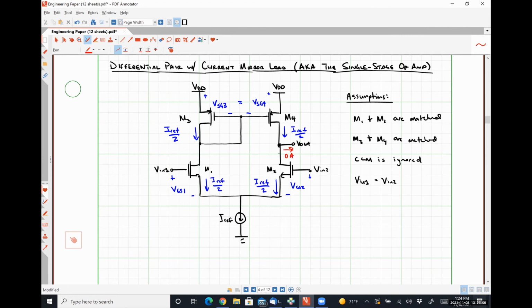And we wind up seeing that the overall current that could flow out to a load is 0 amps, which is exactly what we should expect here. So effectively, we're not going to have any current losses or anything like that. So we're going to see that we reject large scale common mode signals extraordinarily well. Should have a very, very high common mode rejection ratio for this guy. All right.